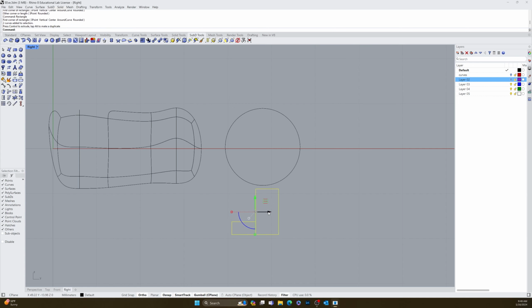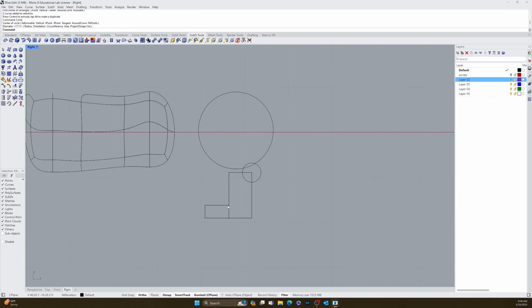let's move this over a little bit. Do one more circle here, just as a guide. All right, and then let's pull into our curves here. So I'm going to go curve here to there. Actually, I want it to curve this way. So click over there. And then I'm going to turn ortho off because it's kind of bugging me. Enter.